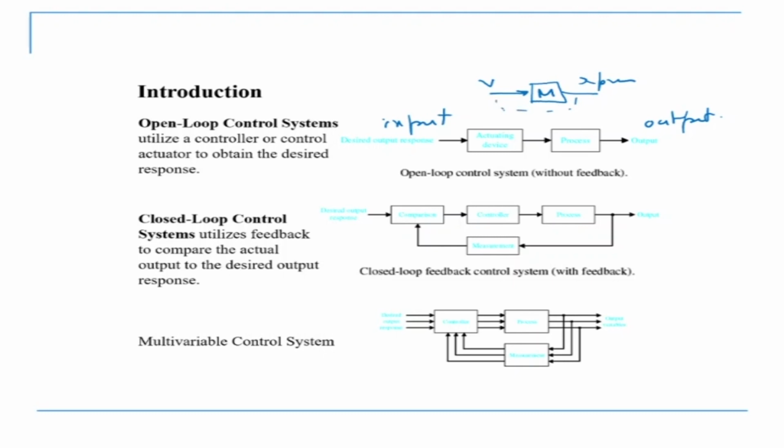In a closed loop control system, you have a closed loop, which is there is a feedback, and this feedback is basically giving the input to the controller about the present position. So this is my theta out, this is the output, and this is my theta in. So this is a comparator which is comparing theta in and theta out. For example, theta in I wanted 10 degrees. So it is comparing what is the present theta, theta in minus theta out, and then taking some corrective action. So this is a closed loop control system.